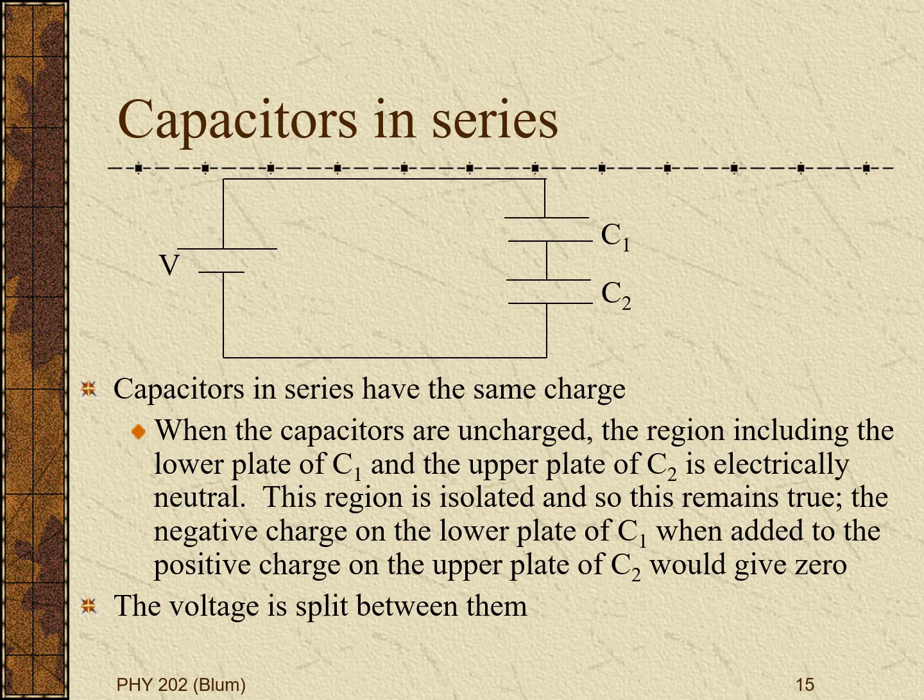Next, we're going to talk about capacitors in series. And we're going to end up saying that capacitors in series have the same charge. Let's just talk about what we mean by the charge on a capacitor to begin with. Overall, a capacitor is neutral. The amount of positive charge on one side and the amount of negative charge on the other are equal and opposite, so that overall it's neutral. But when we say that we are charging a capacitor, we are talking about just one of the plates.